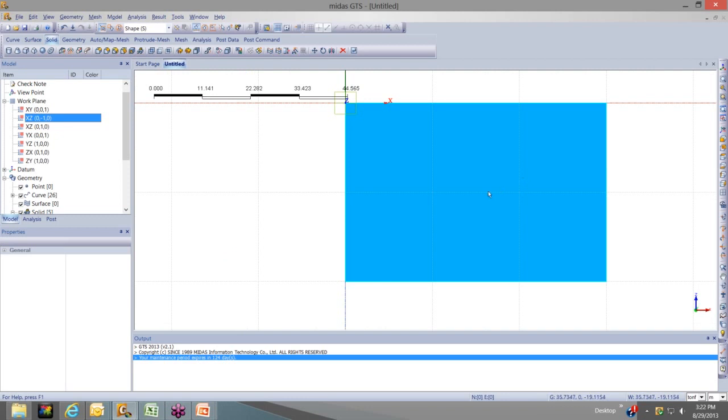And now let's draw some soil strata. As Aaron alluded to, a really great advantage of GTS is that it's able to create very complex or very detailed geometry. For example, in other programs such as Plaxis and GeoStudio, you can only create level strata, but with GTS, you have the option to create asymmetric strata and detailed contours. I'll show you how to draw some asymmetric strata.